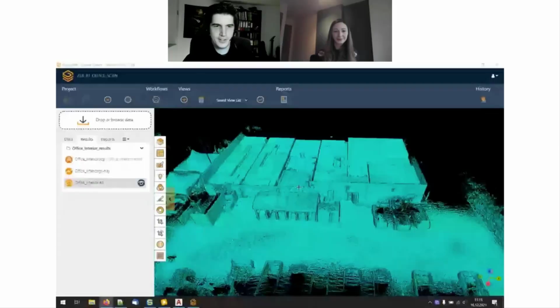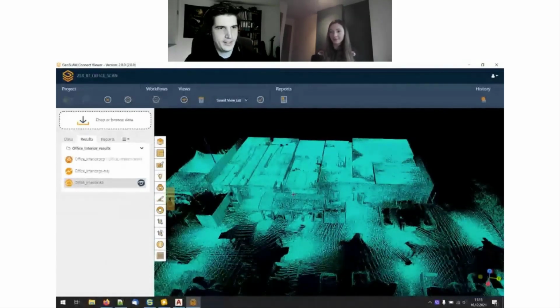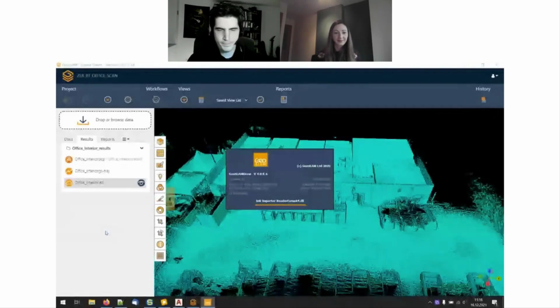But here, let me share my screen, this one. So now you should see that. You see GeoSLAM Connect. I can move around here, but we're not talking about GeoSLAM Connect now, but GeoSLAM Draw. You see I already created a PCP project here. If you want to create it for the first time, go to your results, LRSet, right-click, say open in GeoSLAM Draw, and your GeoSLAM Draw project will automatically be generated. I'll just double-click this one and it will open then.